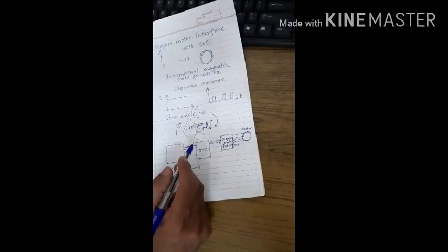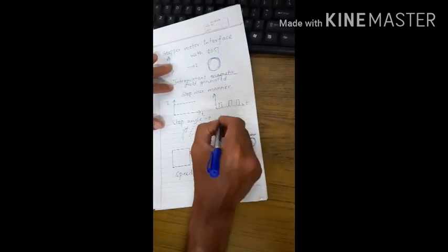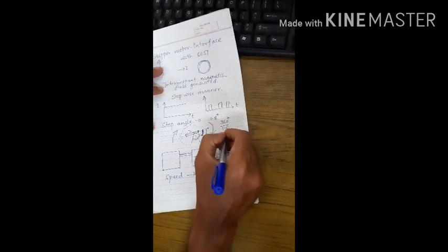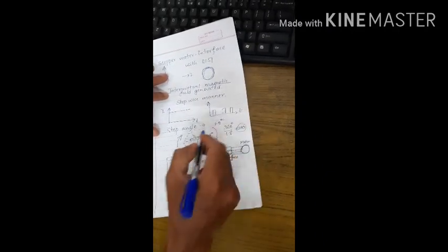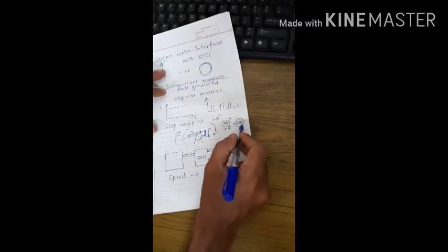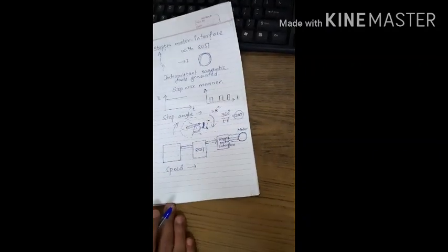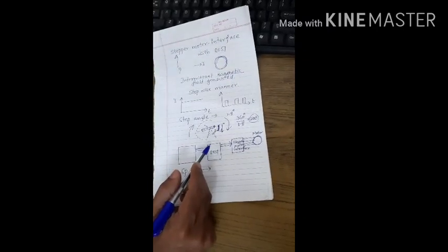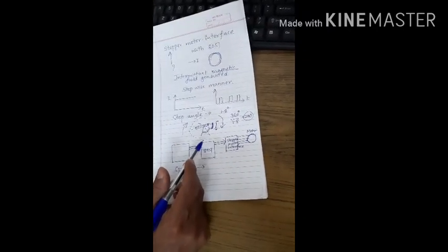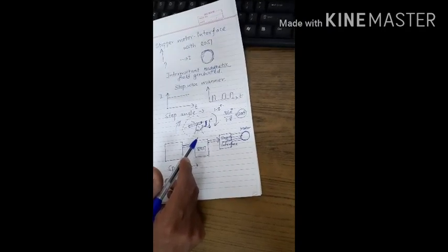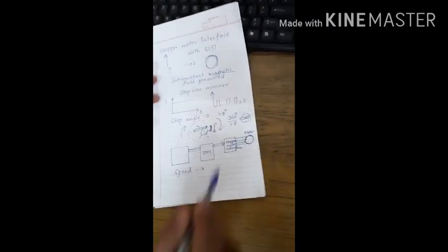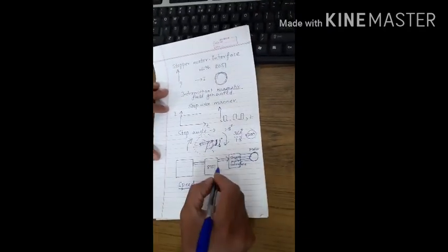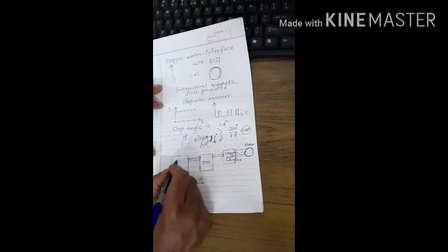The speed of this stepper motor can be adjusted by controlling the delay between the successive steps. The number of steps will always remain fixed. If the step angle is 1.8 degrees, then for 360 degrees it will take 200 steps, as we know. If it is 3.6 degrees, it will take 100 steps. So that number of steps remains fixed. But how you change the delay between the successive steps will decide whether you make it rotate faster or slower. That means you are controlling the step rotation.